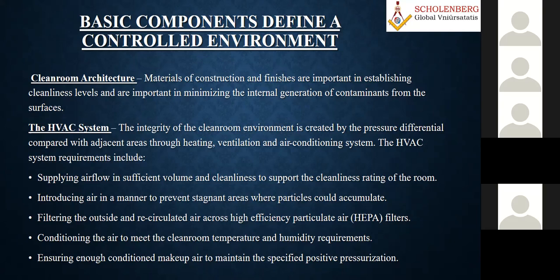So when it comes to the HVAC system, mainly the pressure differential compared to the adjacent area. This also I have told you: the positive pressure. Mainly all the operation, I also mentioned, positive pressure. Why is negative pressure included mostly in the laboratories, kitchen area, and all that? I have already explained that also in the previous class.